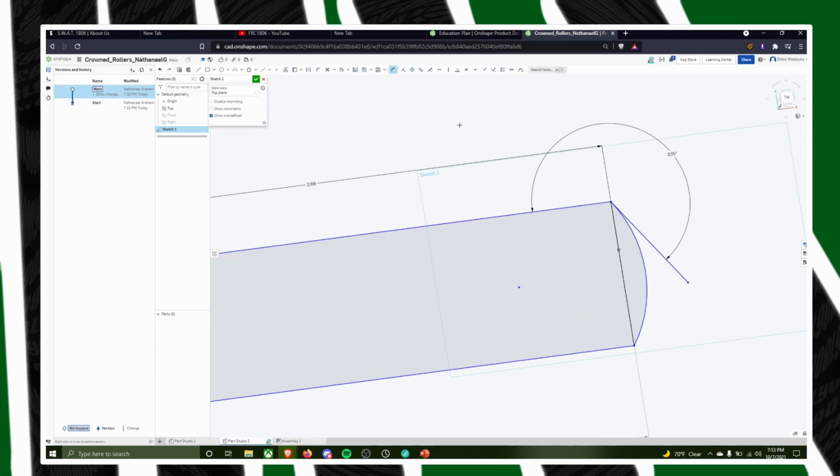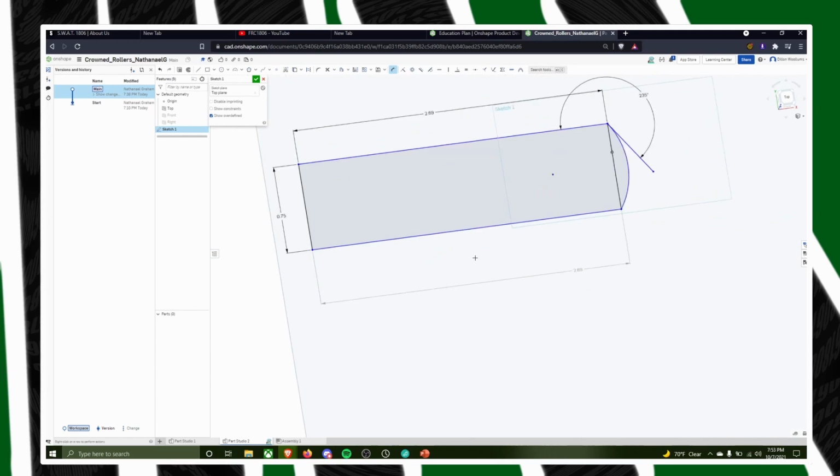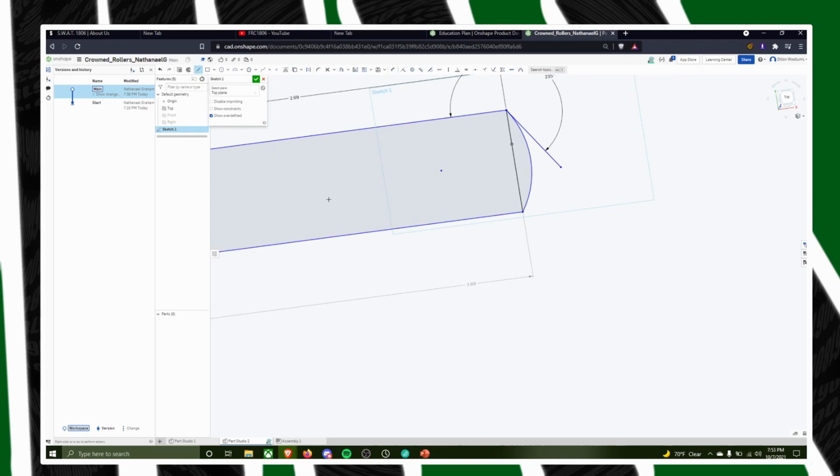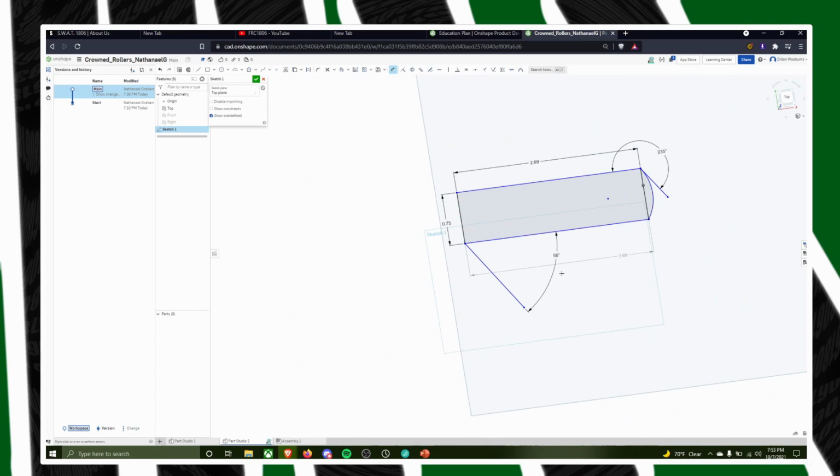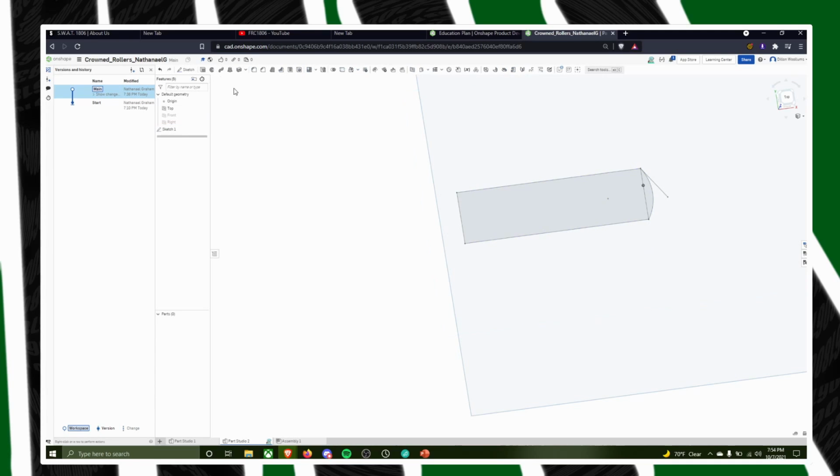Yeah, so you can dimension any kind of freeform angle. You can do something like that too. Like if I wanted to just throw an arbitrary angle here, you can just dimension here to here. And that is exactly 56 degrees, if you ever need to draw something at a specific angle. Get rid of that.